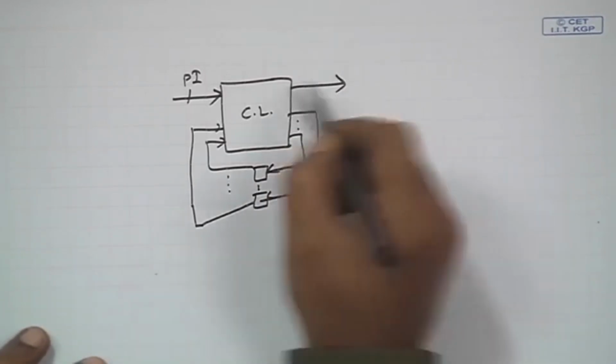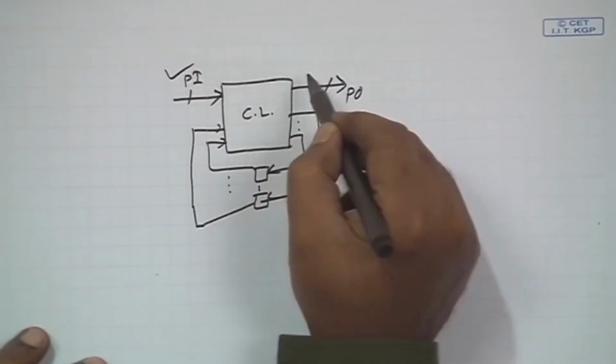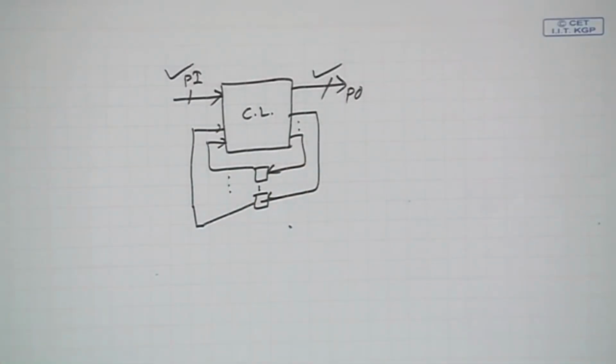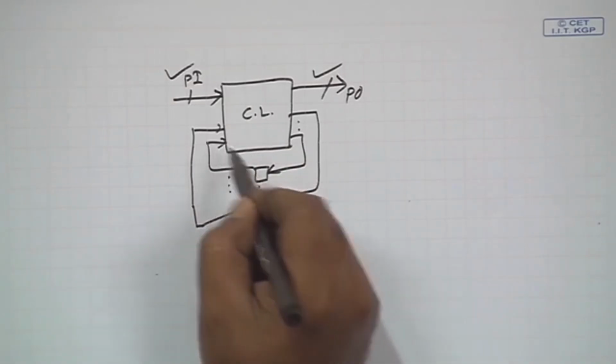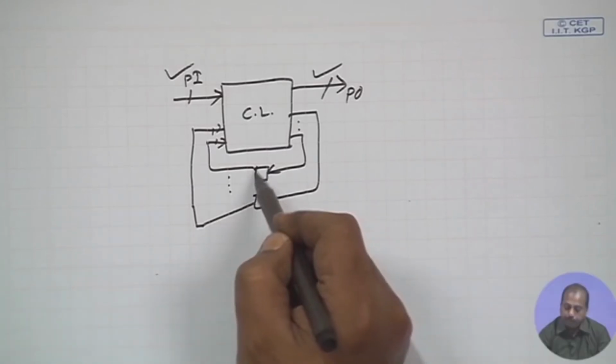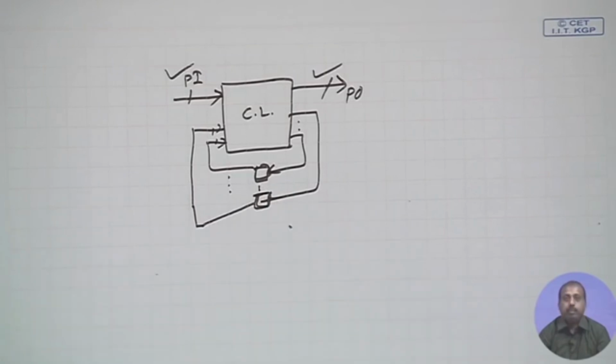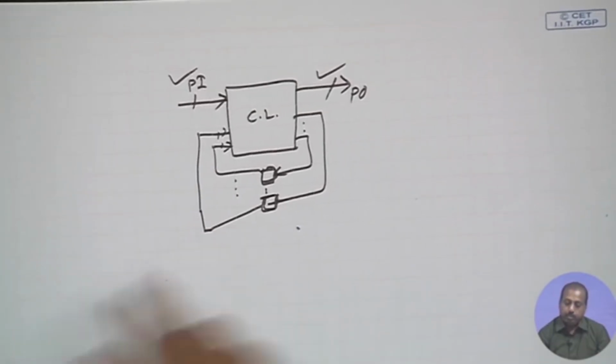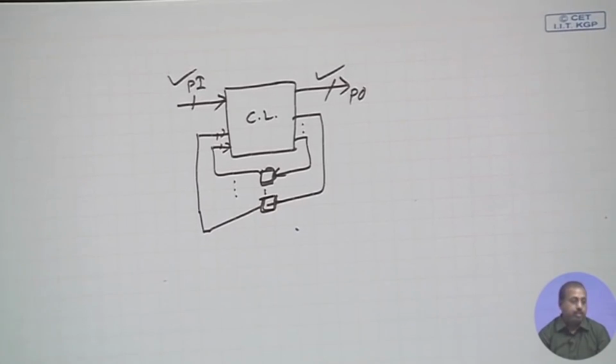Now, you see that these are the primary input and primary output. So, these lines can be controlled very easily and also observed very easily, but it is difficult to control the values that I need to put at this point, because starting with the initial state of the finite state machine, these flip flops will have some value depending upon the state transitions that are effected in the system. As a result, it is difficult to come up with proper state transitions so that we have the desired values at these flip flops. So, this scan design is a transformation that will help us in doing these operations.